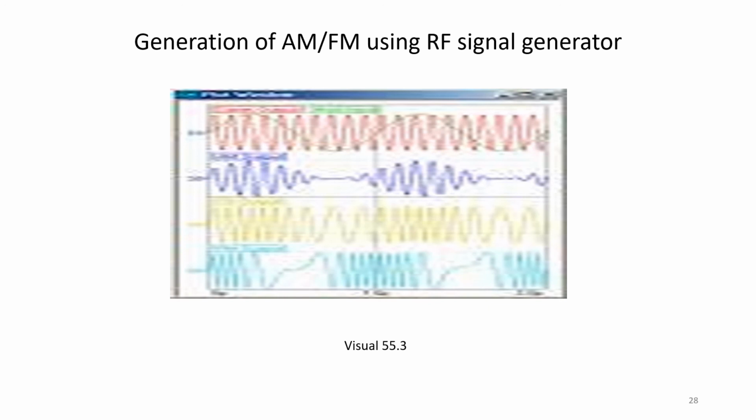You can obtain depth of modulation of 30% with an output impedance of 20 ohms or 40 ohms. The output voltage we can obtain is 50 millivolts. The AF modulation is 400 Hz or 1 kHz. The power supply is 230 volts and 50 Hz. The external modulation source has a frequency of 0 to 5 kHz, and the frequency error is 1%.